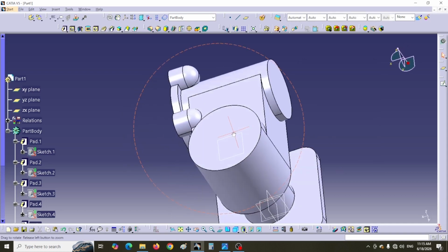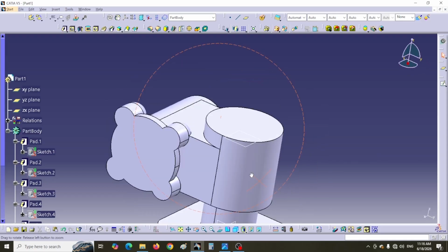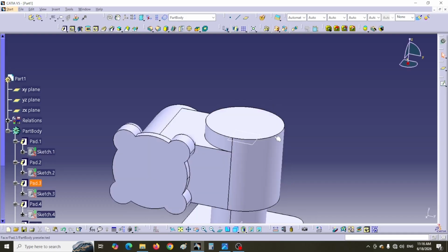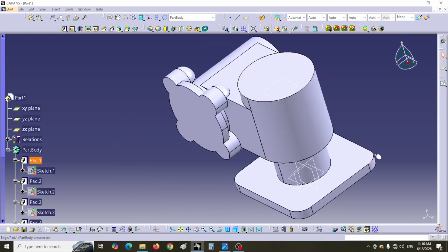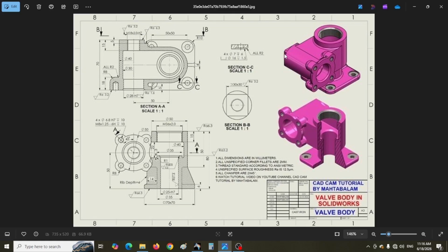Important note, you must draw this part after the flange, otherwise you will get an error when rounding the heads of the smaller cylinders. Of course, it is also possible to move commands in the specification tree. If you look carefully at the shape, there is a rectangular part on the other side of the horizontal cylinder.